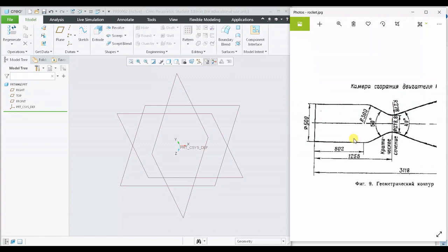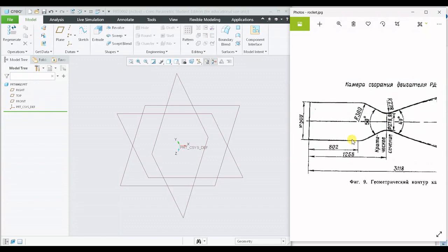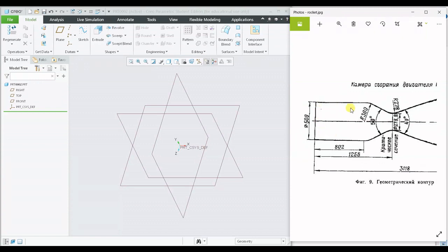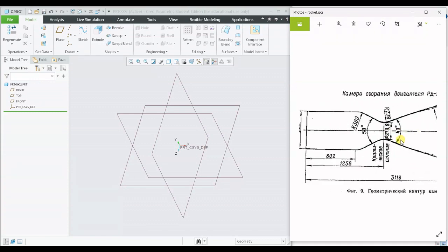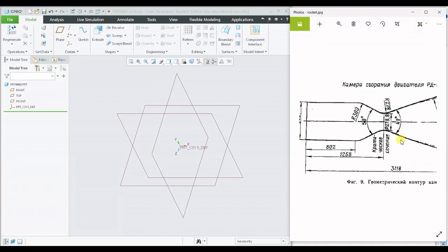And for the sketch, we only have to create half the sketch or half the cross section of the total geometry given to us. So in this case, we will try to create the upper half. So we will be having the sketch ready with us, and we will also have the axis of revolution, which is going to be the x-axis. So when we are ready with both the things, we only have to use the revolve option and create the revolve geometry.